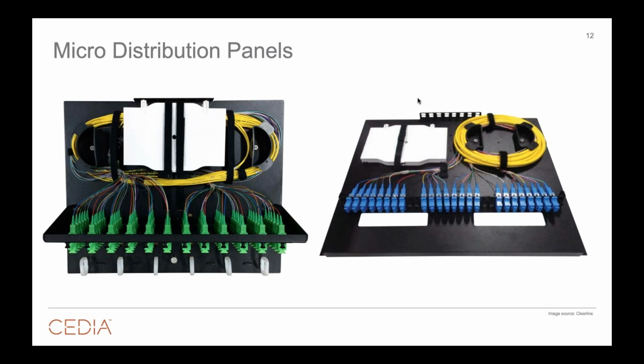And that's why these rack trays, these panels are so important. Whether you're dealing with a wall box, whether you're dealing with a rack tray, if it's designed for fiber, it's designed to take into account the tiny little strands and manage those, secure them, keep them from wiggling out of the connectors or keep them from being pinched and breaking, okay?